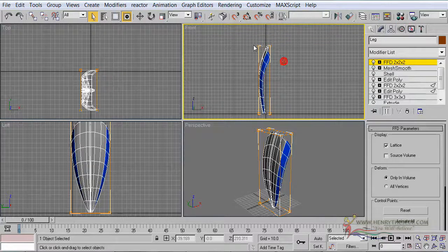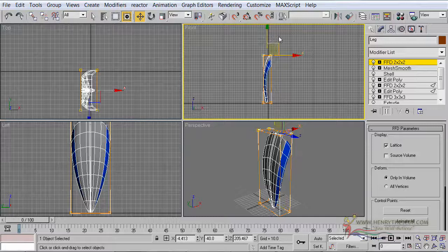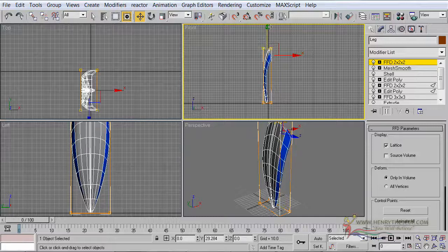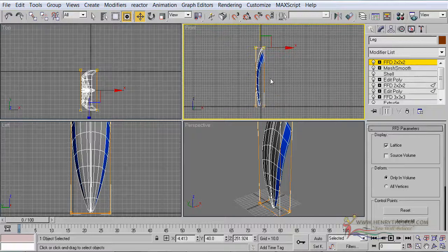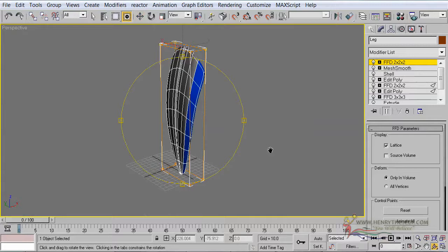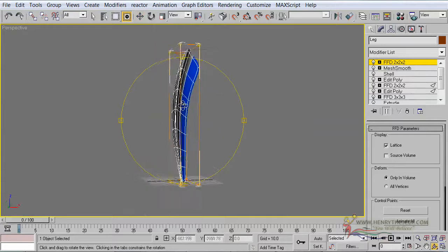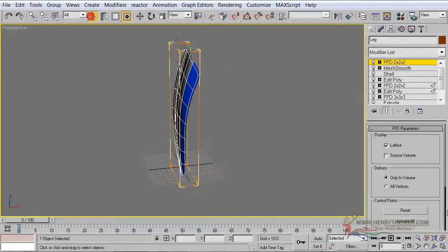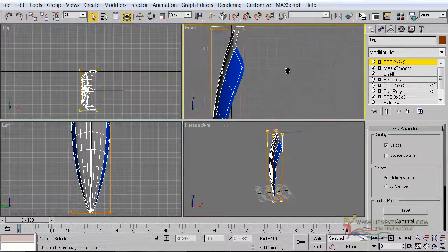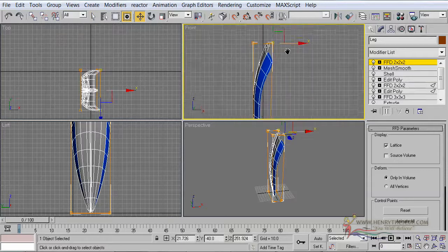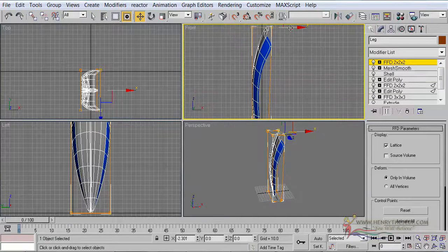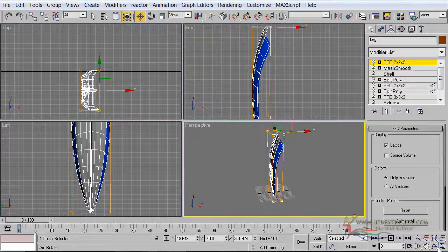Click on the control points, and we simply want to drag that part of the leg further upwards, to give us of course a taller leg, so that more things can be fitted in the middle. Yeah, this is quite appropriate. And then we're going to select the control points just on this upper side of the leg, and those we just want to push inwards like that. Not too much, remember you must never overdo anything.